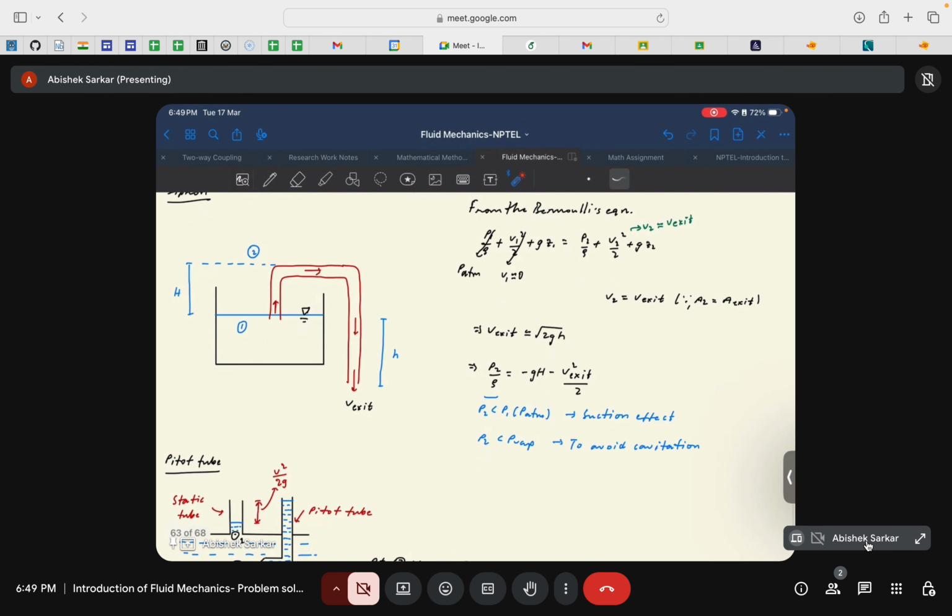Now, considering that the width of the pipe remains consistent, the velocity at point 2 would be the same as the velocity at point 1 because of the continuity equation, since area A1 is equal to A2, so V1 would be essentially equal to V2. Again, using Torricelli's law, which is something you can look into, we can approximate the exit velocity to be equal to root 2gh. It's just a rough approximation, but let us consider that.